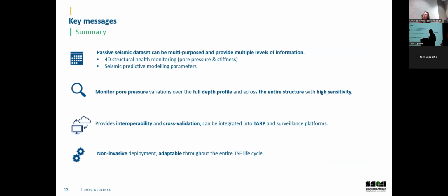So yeah, let me finish. Key messages. The passive seismic dataset can be multi-purposed and provide multiple levels of information, both in the monitoring and extracting of geotechnical parameters. Monitoring pore pressure variations over the full depth profile into the foundation, if we have the frequencies to allow that, and we can do it across the entire structure with high sensitivity.